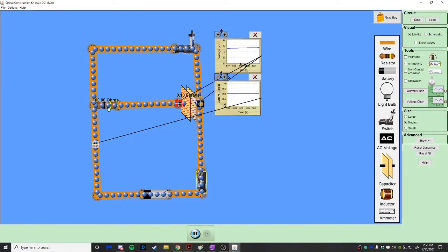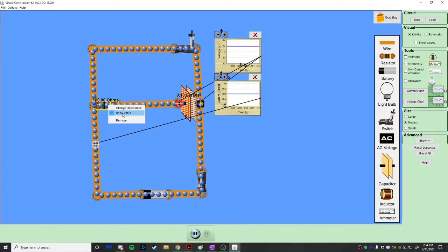It's like time. You're controlling time in a circuit by simply modifying one of these two values. Do you understand the power of that? The ability to take these devices and put them in a circuit and have that circuit have a time control associated with it? You can control how long it takes for this object to charge up, which means you can control how long it takes for a light bulb to light up in the circuit, or a windshield wiper to go off. You control the time simply by changing these things, right?